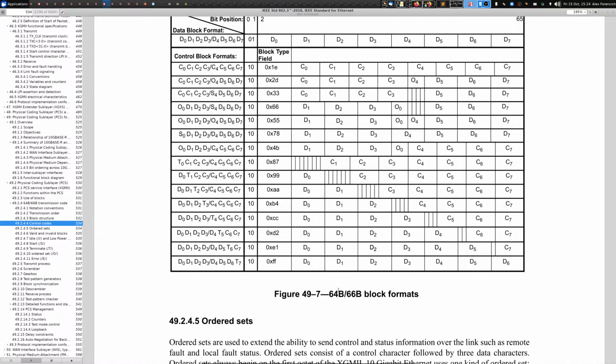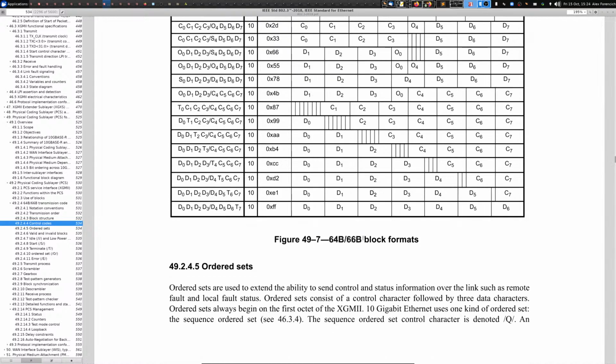Anyway, there's a bunch of different line codes that are used, and they all serve similar purposes. They all have slightly different characteristics. Mainly, the most obvious one is in terms of the overhead. So 64B/66B, that's something like a 3% overhead. For 8B/10B, that's higher. For 128B/130B, as in PCI Express, it's lower.